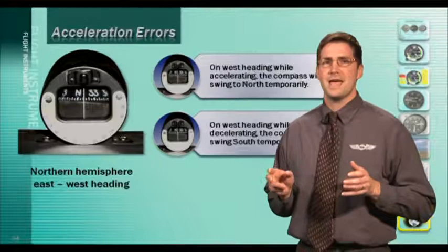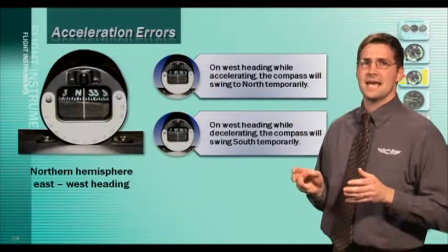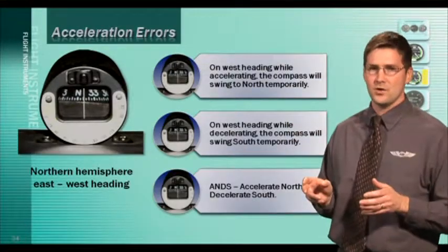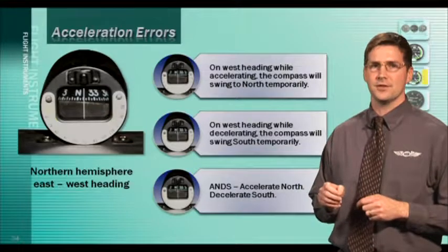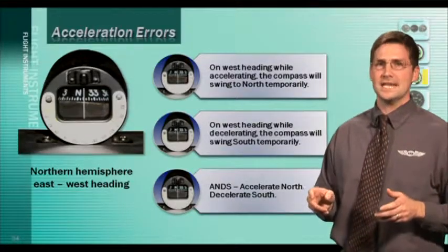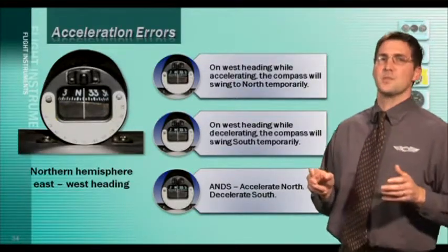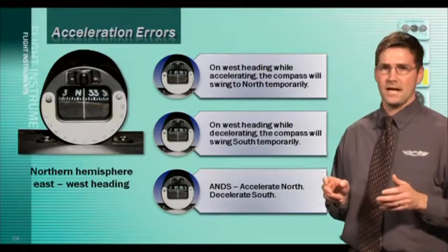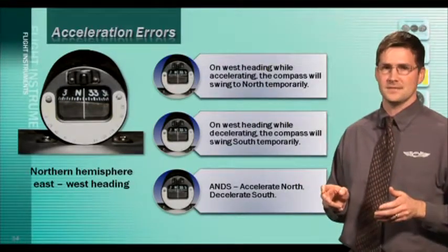Remember the acronym ANDS, A-N-D-S, and it stands for accelerate to the north, decelerate to the south. It occurs only on easterly or westerly headings. The compass will indicate correctly when accelerating on northerly or southerly headings.